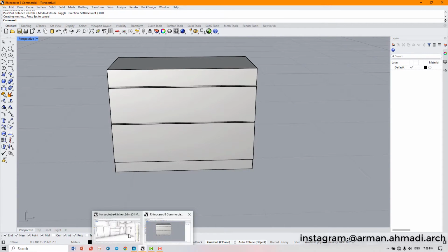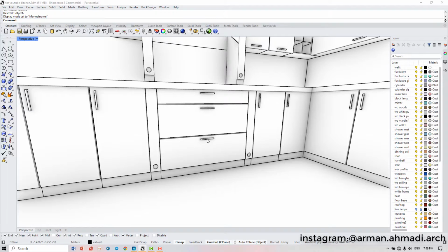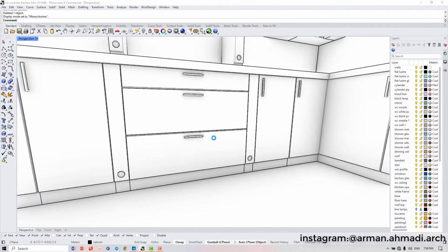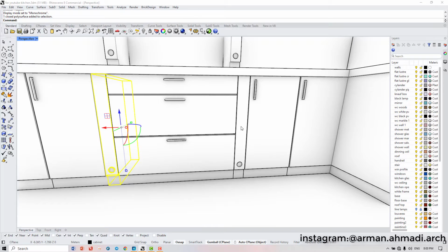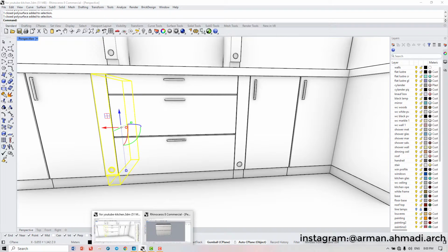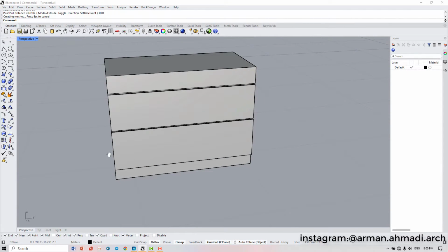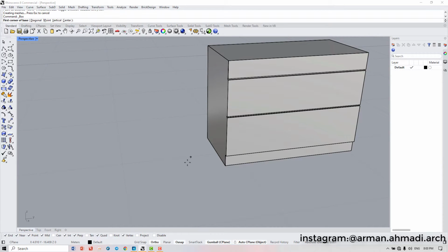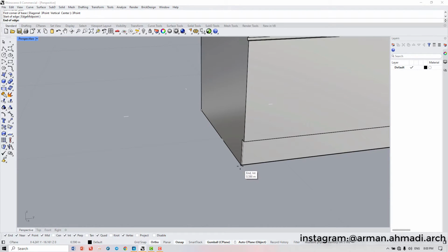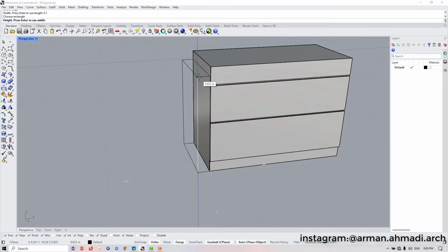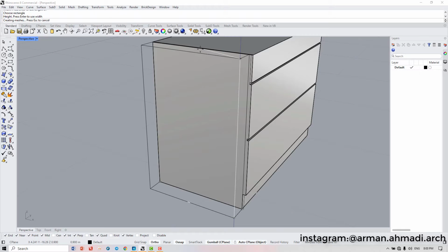And the other thing we have is these door handles, and also these decorative things here. So I again go to here and I draw another box using 3-point feature. Yes, 3-point feature. Okay, for example 0.1, which is 10 centimeter. Hit enter and come to here.